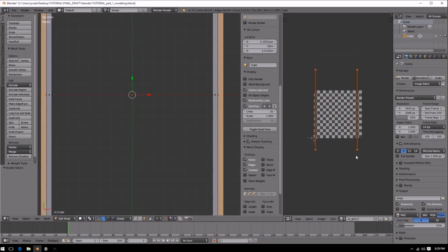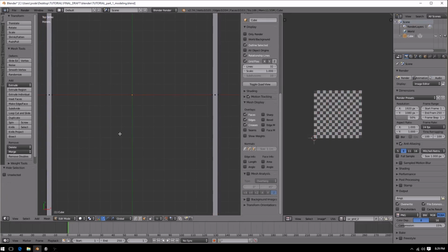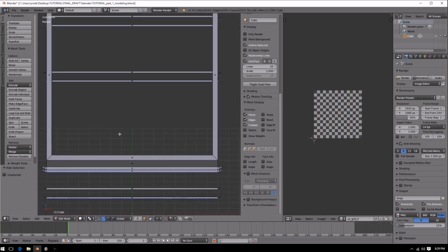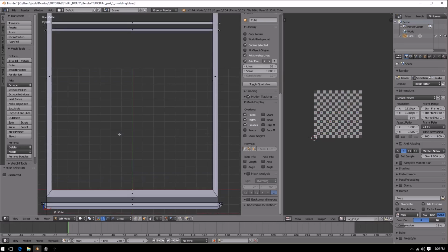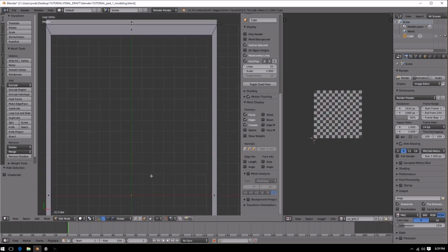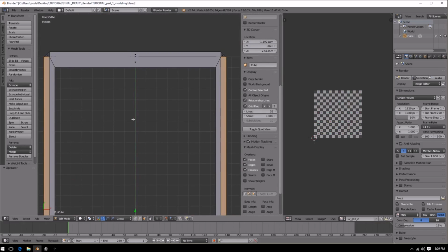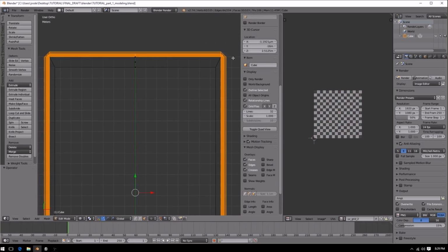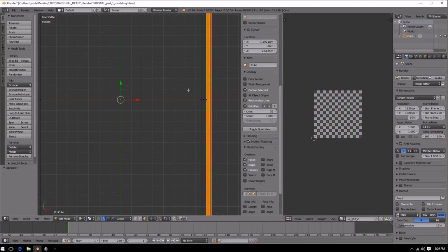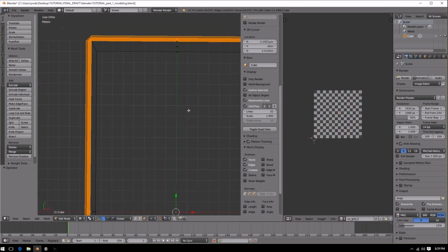And then highlight these and move these off to the side. Hide that. Alright, so now we've got all these extra pieces actually. I forgot to go into wireframe mode from the top view, so we didn't select those. Let's go back into the top view here and, carefully panning, I'm going to undo that selection. I'm going to go back into wireframe mode and select all of these extra pieces that I missed on the first go here because of my oops, that's the window. It's my incompetence here, I guess.